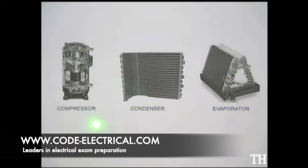Now, the three major components of an air conditioning system are the compressor, the condenser, and the evaporator coil. The compressor is located in the outdoor unit, the condensing unit, along with the condenser coil. The evaporator is located on the inside air handling unit, called the A coil. The function of the compressor is to keep the refrigerant moving through the system the entire time. The condenser's job is to collect the heat from inside the home and release it outside the home, whereas the evaporator's job is to cool the air inside the home.